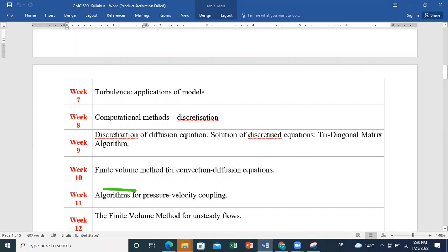So you can use CFD, you can run your simulations with different turbulence models, and you will select the one which will give you the closest result to your experimental results. So this is what we call model validation. So whenever we develop a CFD model, to make sure that it's working appropriately, we can compare with previous data from literature, or also we can compare with experimental results.